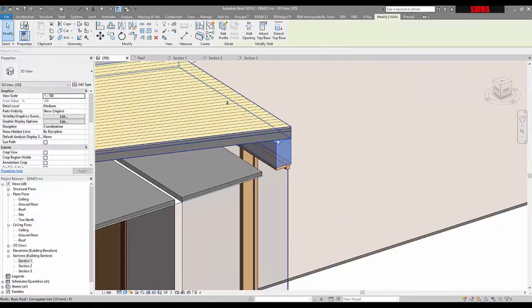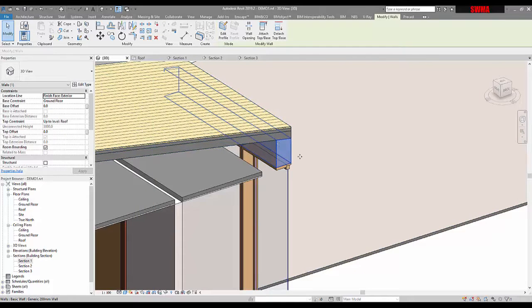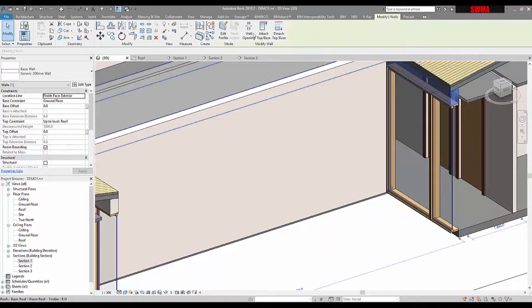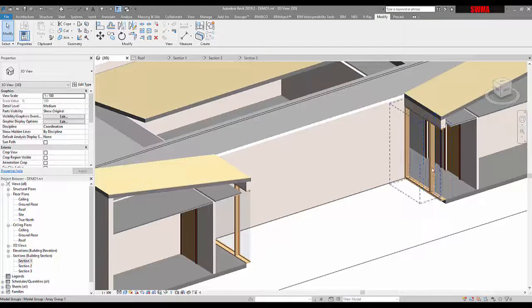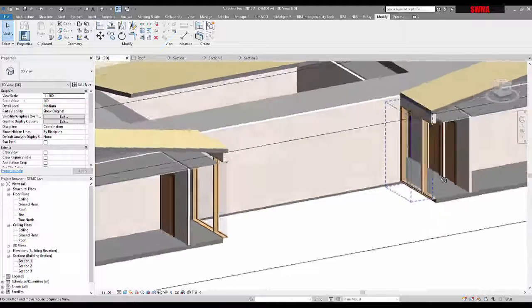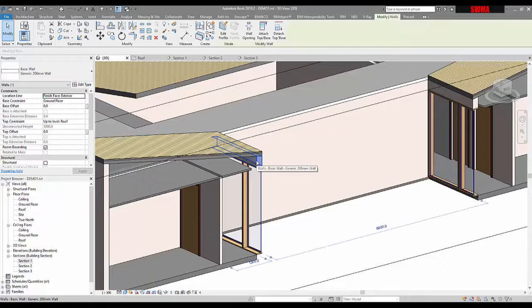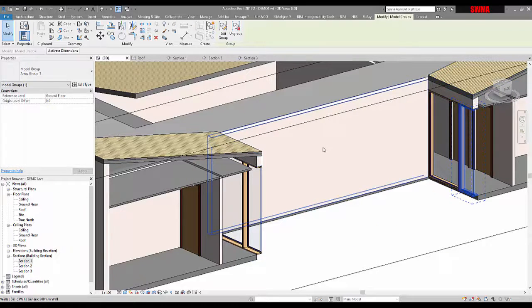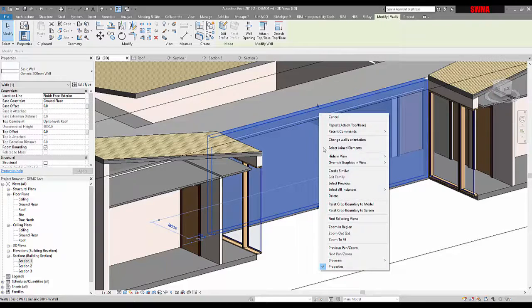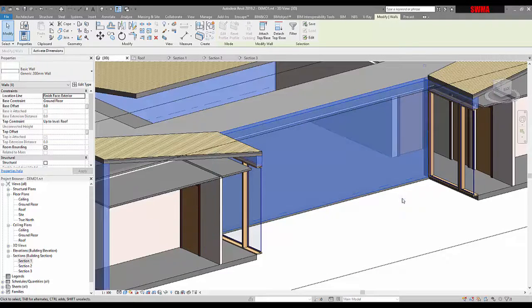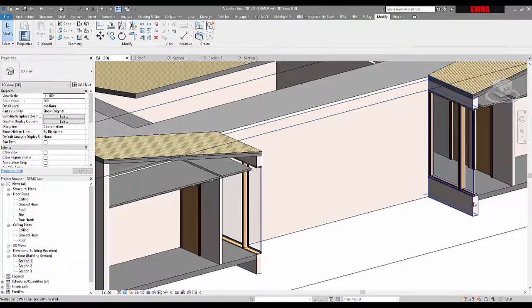Here, this wall isn't cleaning up, so I'm just using that tool again, clean up. That cleans that up. And over here, attach that one as well. So really just helpful little ways to view and inspect the model. Other things you might notice here is the wall isn't going down below that ground level. So I can grab that wall and that wall, or another thing I could do is just grab all instances in the entire project of those external walls, and I want them to be sitting at ground floor, but they may need to go down beyond the floor slab, and there could be a trench, a footing for them to rest on. So I'll just do a base offset, maybe of 600, and now they go down beyond.